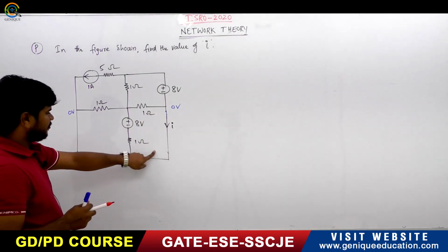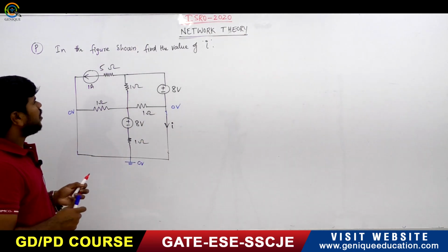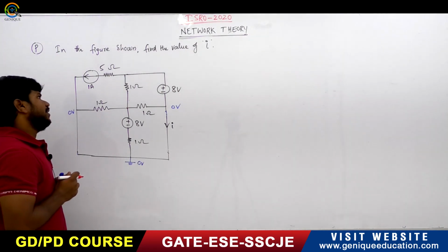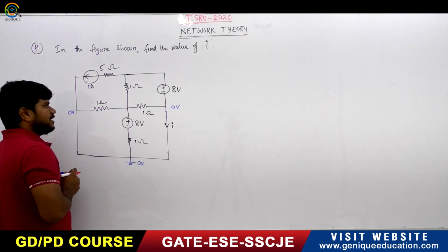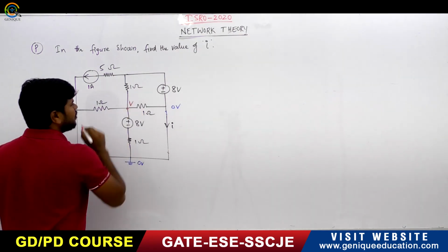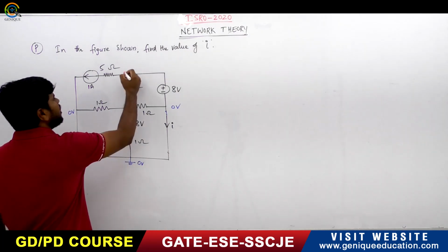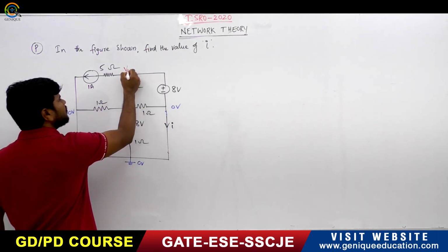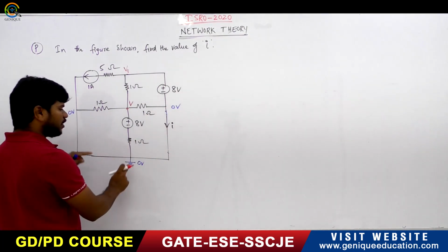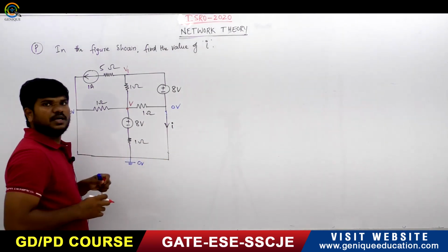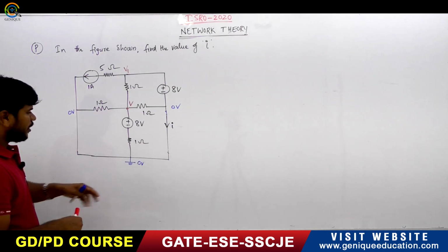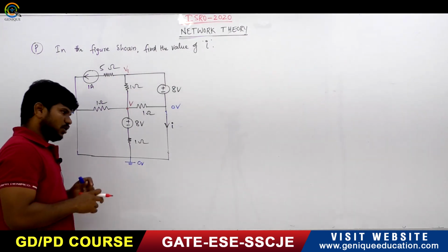Okay, there is a wire from here to here. Now I want to apply the KCL here. So let us suppose this is one node. I am assuming the node voltage V. Here is one more node, I am assuming this one as V1. And all the remaining nodes are this one only. All node voltages are equal to 0, because I am assuming 0 volts here.